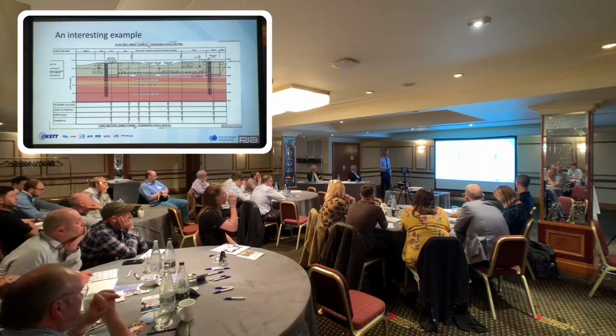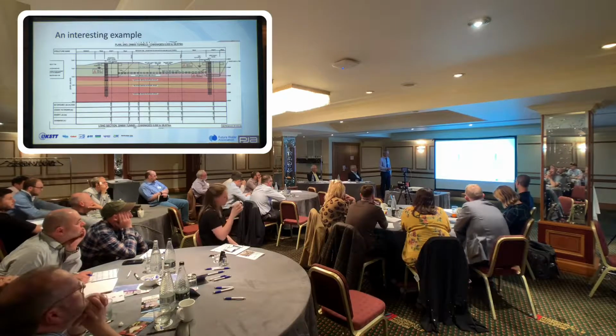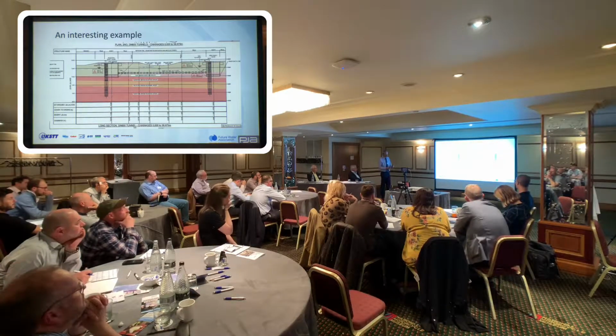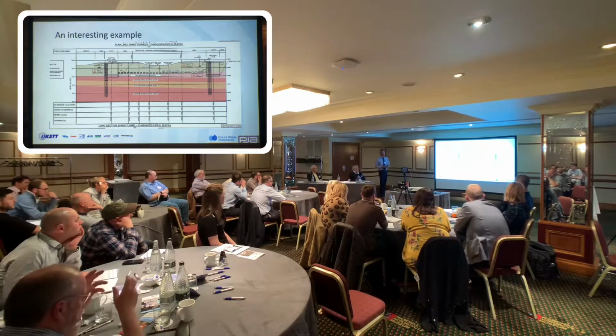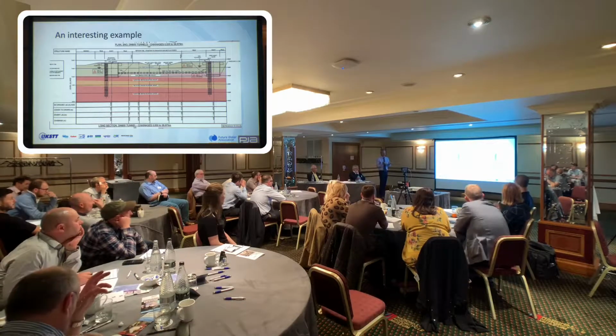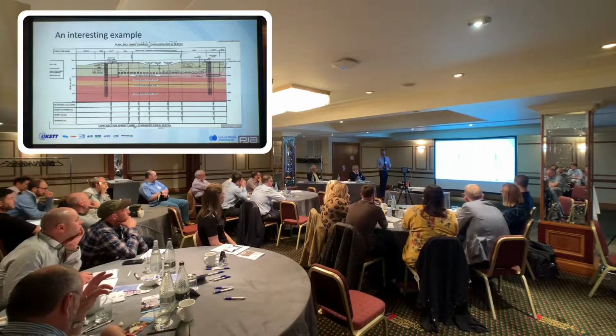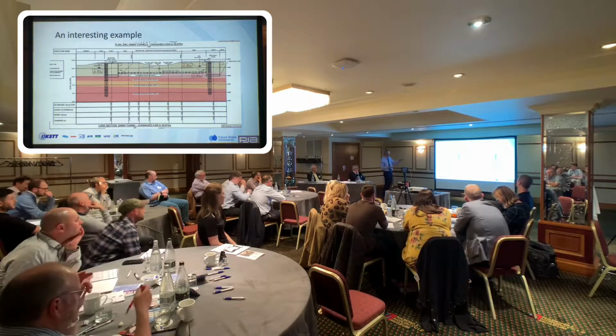And the breakout, break-in here was dealt with by using a GRP sandwich on the outside of the shaft, rather than putting a concrete wrap on the shaft. At small diameters, they're about 25 mil thick, and they're sufficient to resist water loading over a small span when you're launching a small machine.